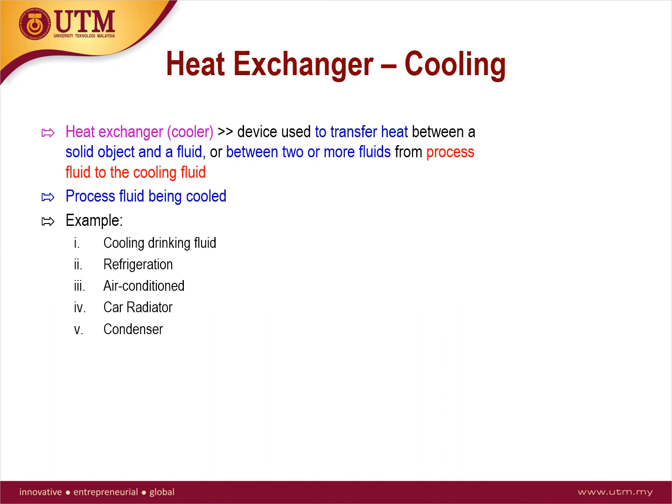One of the widest uses of heat exchangers is for air conditioning of buildings and vehicles. This class of heat exchangers is commonly called air coils or just coils due to their often serpentine internal tubing. Liquid to air or air to liquid HVAC coils are typically of modified cross-flow arrangement. In vehicles, heat coils are often called heater cores.